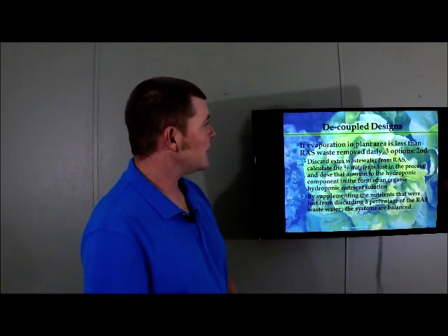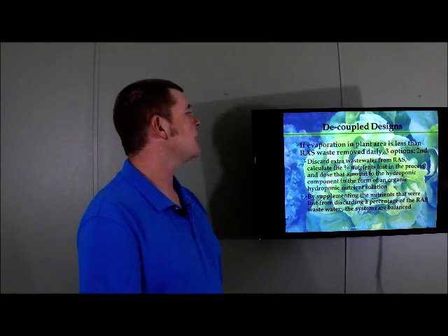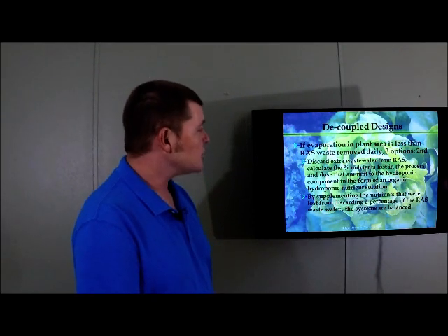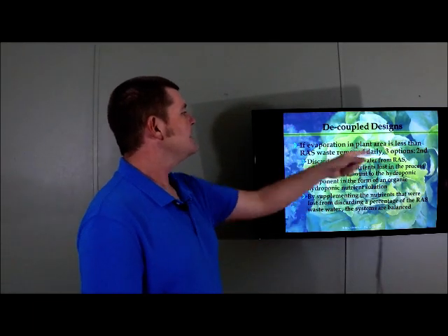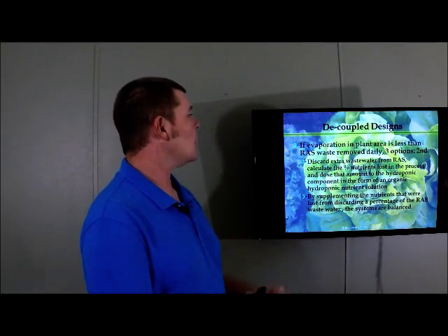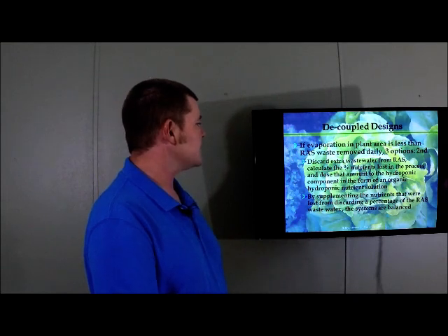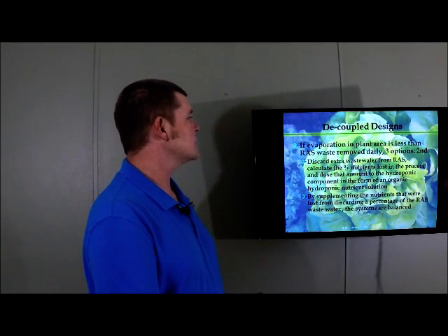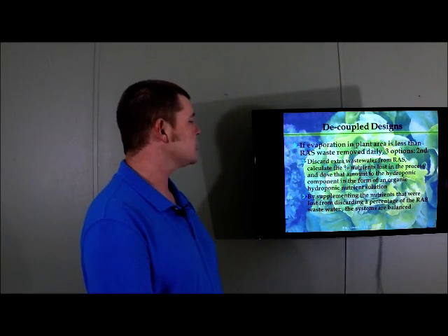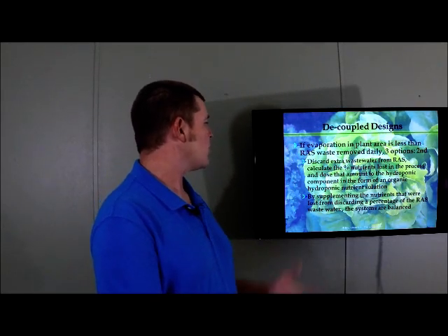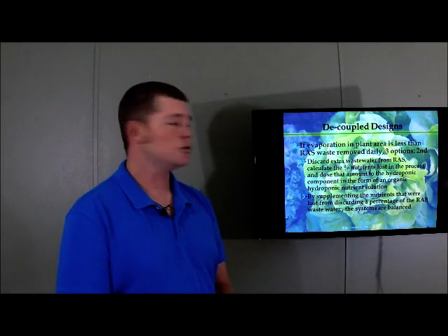If evaporation in plant area is less than RAS wastewater removed daily, you have three options. The second option here is to discard the extra wastewater from the RAS, calculate the percent of nutrients lost in the process, and dose that amount of nutrients to the hydroponic component in the form of an organic hydroponic nutrient solution, okay?